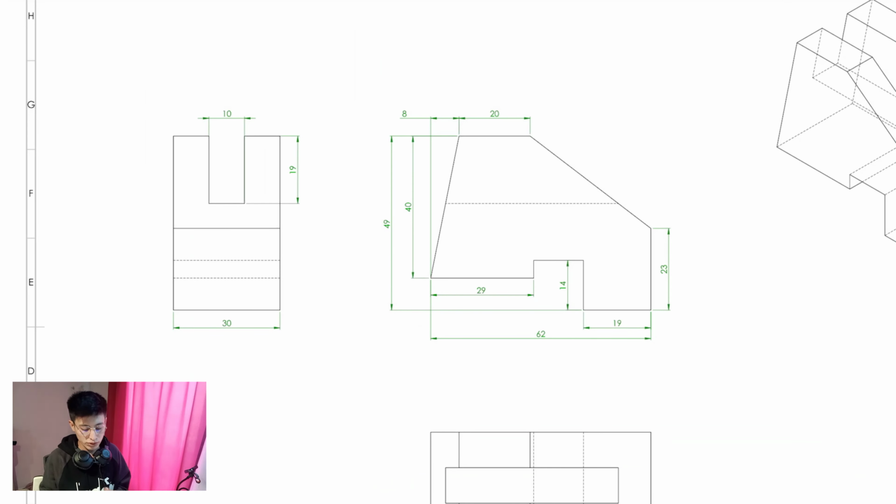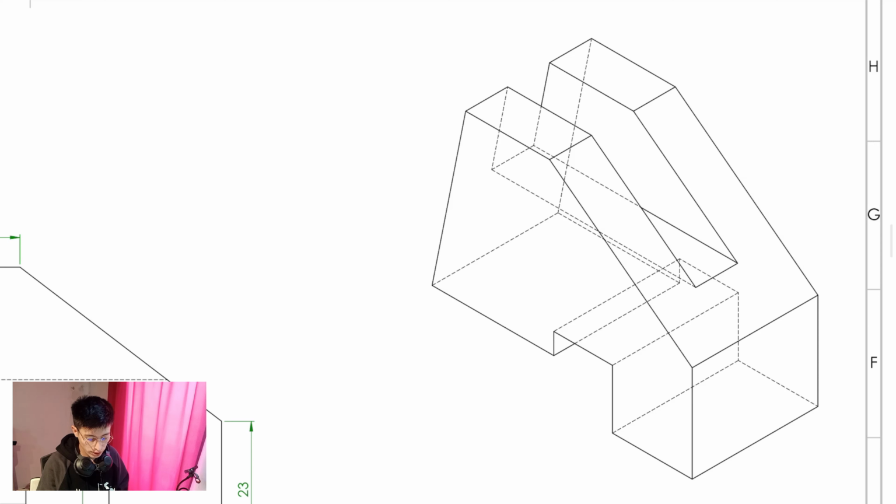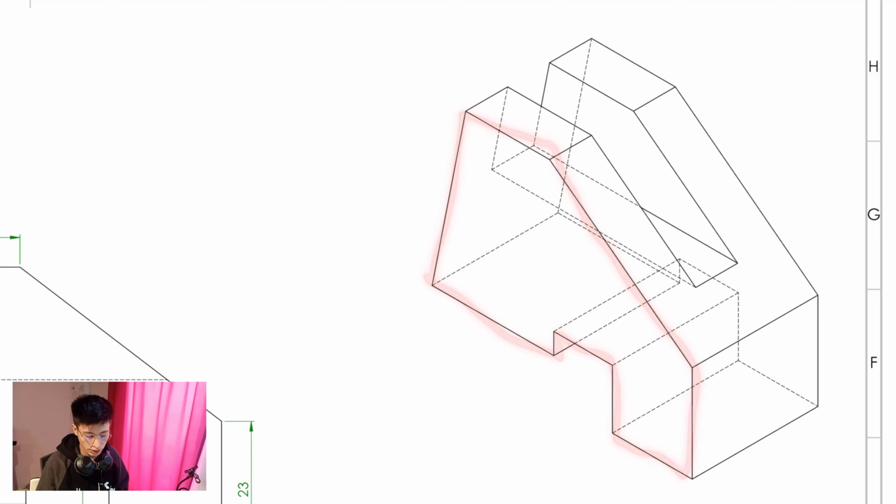We will create the following 3D model using SolidWorks. Basically, what we have right here is this shape extruded along this direction. Of course, we have to take into account that there is an angle generated right here, but that information we will see along the construction of the 3D model. And we have a rectangular shape extruded along this direction as well. So a pocket. It is not an extrusion.